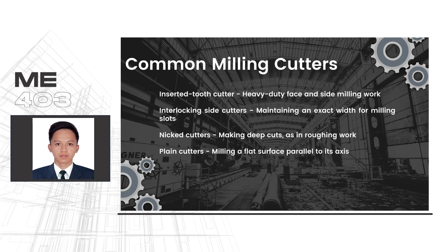Inserted tooth cutter, characterized by long life, it is used for heavy-duty face and side milling work. Interlocking side cutters, designed to maintain an exact width for milling slots. Nicked cutters, suited for making deep cuts as in roughing work. Plane cutters, used to mill a flat surface parallel to its axis.